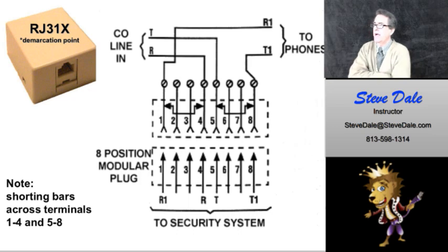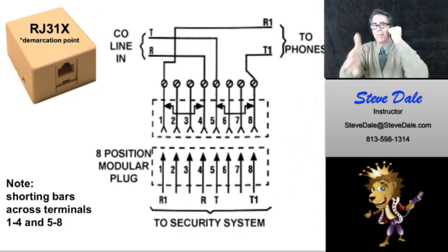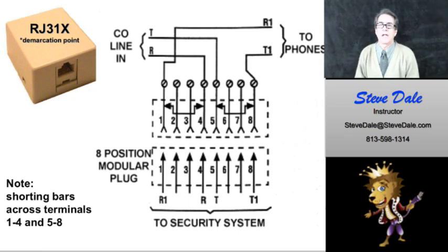Some of you guys who have been in the alarm business for a while can tell that right away, because if you're sending a signal from your alarm panel and you pick up a house phone and you hear it dialing out, well, guess what? You don't have supervision of that line. Those phones aren't disconnected. When you trip the alarm panel, those phones should be dead, okay? But if you trip the alarm panel and you can listen to the handshake and the signals and the kiss off from the alarm panel to the central station, you can hear it on the phone. That means the phones are tied in parallel on top of those tips and rings.